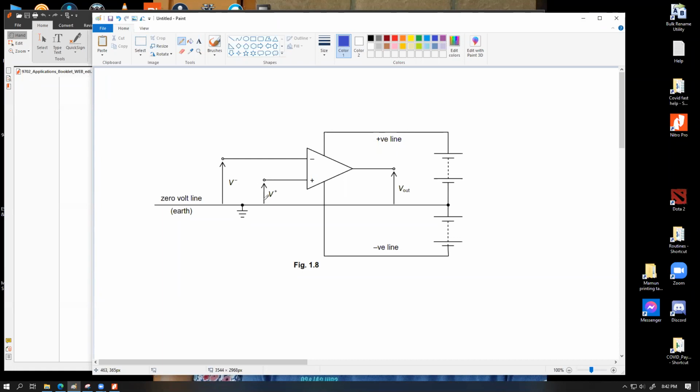But you have to understand one thing: typically if we have similar directional arrows for a voltage symbol in a circuit, they mean they are similar voltage. It means in this case either both of them are positive voltage or both of them are negative voltage. They are not opposite type. The arrow lengths do not mean the value of those things, but the direction of the arrow represents the type of voltage. Similar direction arrows in a circuit mean similar type of voltage, both positive or both negative. That's very important information.